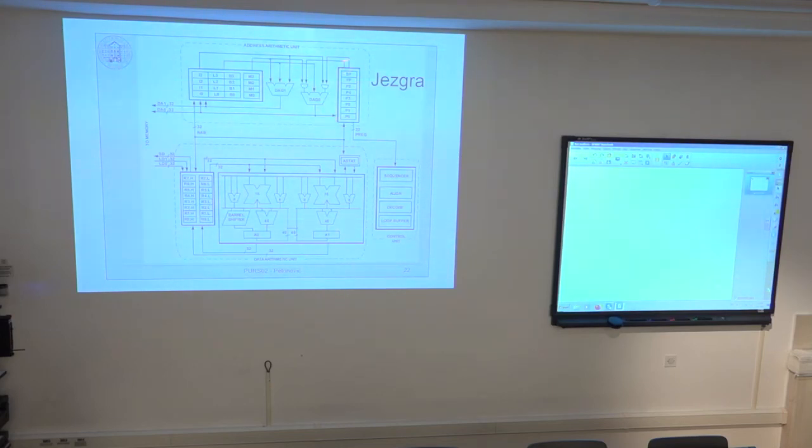For example, stack pointer and frame pointer are used to implement the stack or to implement the frame in some higher level language implementation in C. So these 2 are dedicated, while the remaining registers, P1 to P5, are general purpose address registers, which can be also used as a source of effective address.